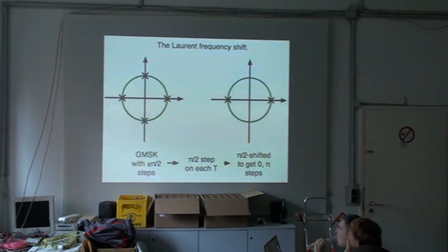So now, instead of having a signal that steps plus and minus 90 degrees, it now steps either 180 degrees or doesn't move at all. The way you apply an ongoing frequency shift, like an ongoing phase step like that, is by frequency shifting the signal. So you're going to frequency shift the signal by 1/2 of, but actually I think it's by 1/4 of the symbol rate.